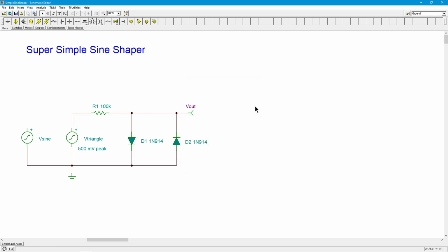Now, if you're thinking, well, okay, but I only have 300 or so millivolts out of this thing. What am I going to do with that? It's not big enough. Well, you can run it into a little op amp for an amplifier and crank that signal up to several volts, 10 volts peak. Okay, that you can do.